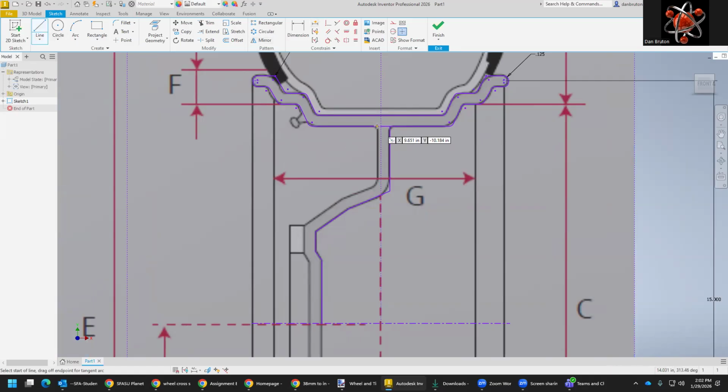I think the only difference you're going to see is basically where this wall is right here. This one wall, you would just change the design all the way up until this point, and then everything else would be the same. So this is our little raised area outside. Then come back over here and then back down. So let's put a couple of fillets in there now. I think we might have to cut this one up into pieces. So let's delete this one and that one, and then try to connect the dots like right here to right there, and then right here to right here. So we wanted to make a solid shape that we can revolve around.